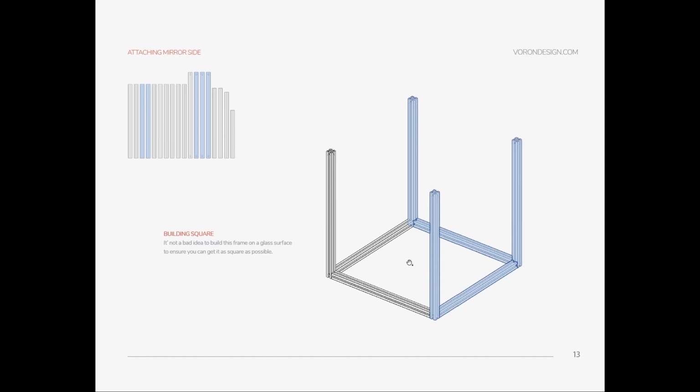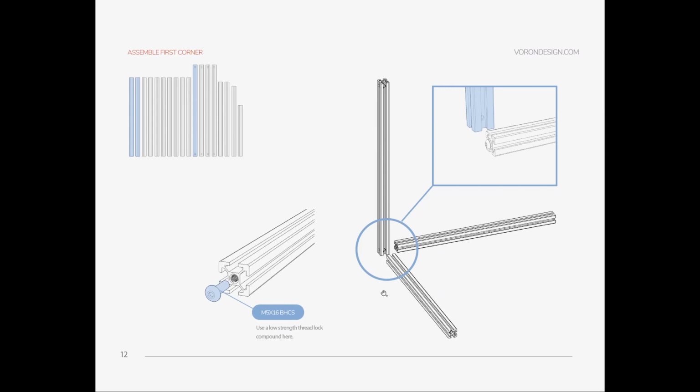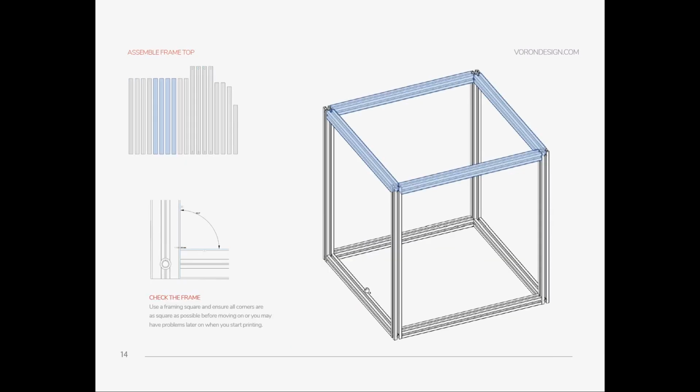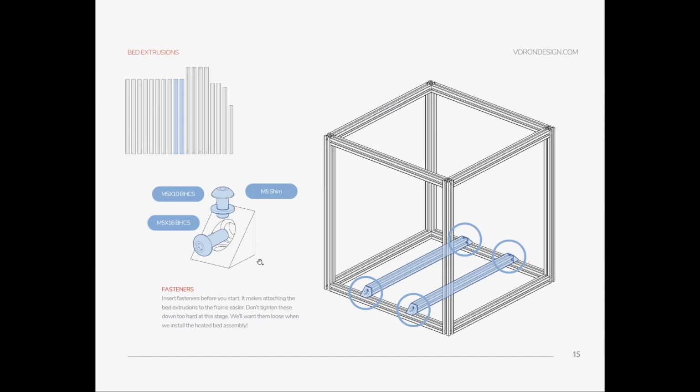Then you will be fine, because later on you will mount the parts also, and that will force your frame to be square. So keep in mind these diagonal measurements under 2 mm, and you'll be fine. And using a flat surface is a big deal. It's really helping. Keep in mind that also. Yeah, it's explaining the squareness.